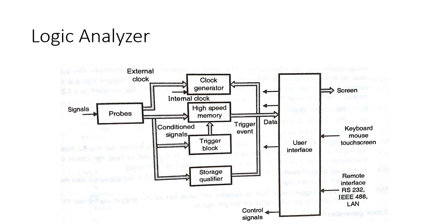In that case, a logic analyzer will be able to sense and display the address bus, data bus, memory read, memory write, IO read, and IO write signals. All these tasks are achieved by this logic analyzer. That's why this is a very important instrument in the digital domain, we can say.